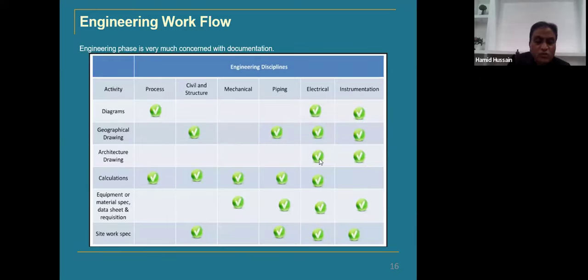And then site work, of course, will be, so process will not, if you see in this one, piping, and after that electrical will also make their diagrams, SLDs, and their required drawings, and their MCC drawings, electrical drawings, and their data sheets for motors, and then all those procurement and construction drawings. They will make location layouts, and distribution, lighting, and other things.